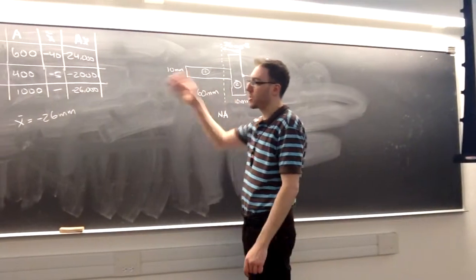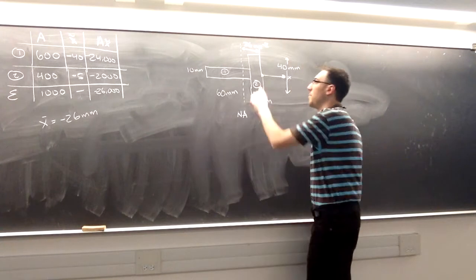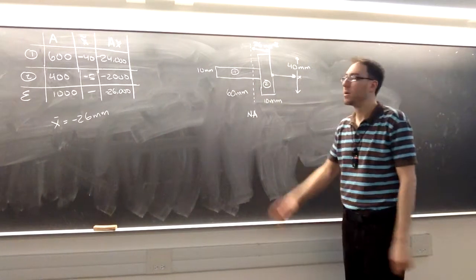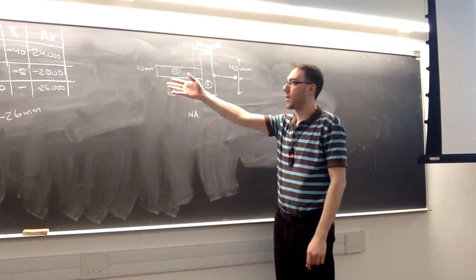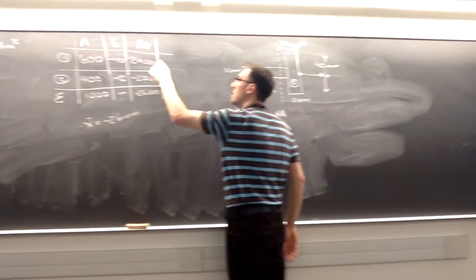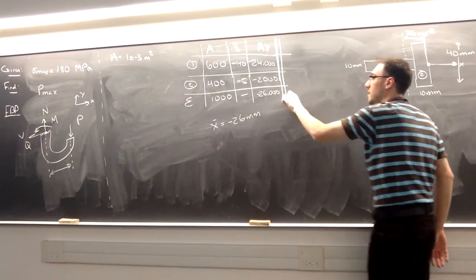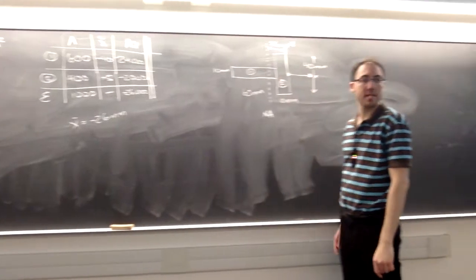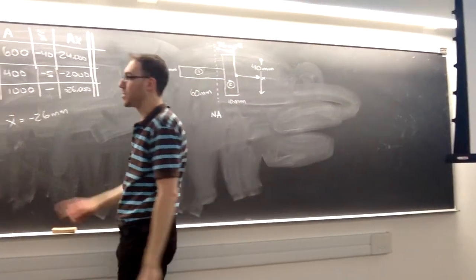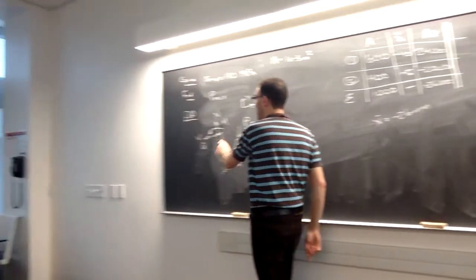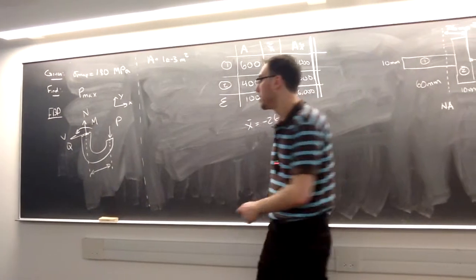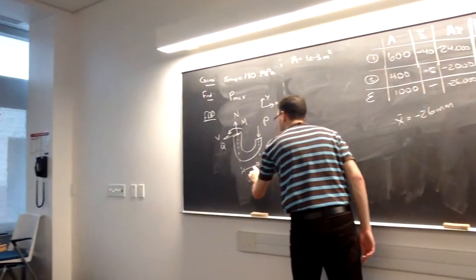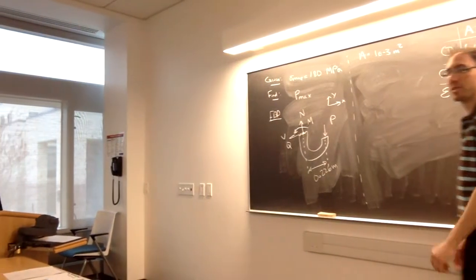Okay, so stick with that original coordinate system I established. If I place x right and now z up, I'm really finding how far in the x direction is this centroid. So if I go through the first part of the table, I find it's to the left of the axis by 26 millimeters, which means the distance between P and the Q, where the centroid is located, will be 200 millimeters plus 26 millimeters. So this distance will be 0.226 meters to stick everything in base units here.